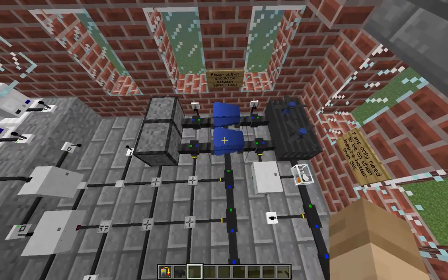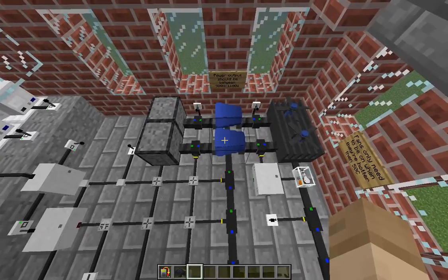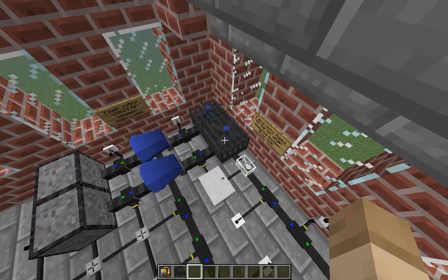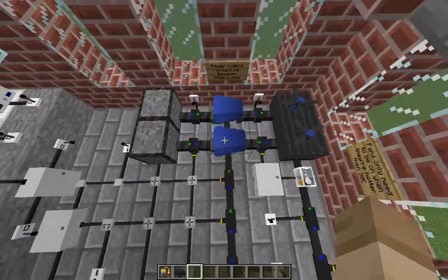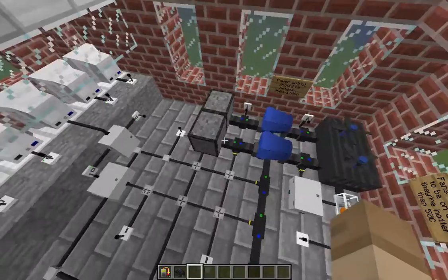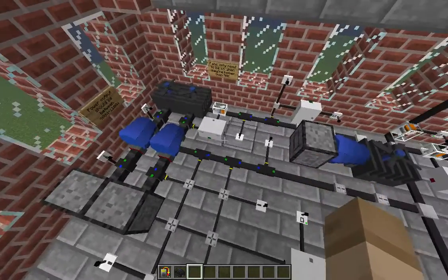The 50 volt turbine's nominal power output was 300 watts, so I had about 1000 watts going into my coolers, and with the 50 volt coolers, it just couldn't keep up. So that got hotter, it couldn't get to that 53 volts, yet it kept on telling it to produce power, and it exploded.